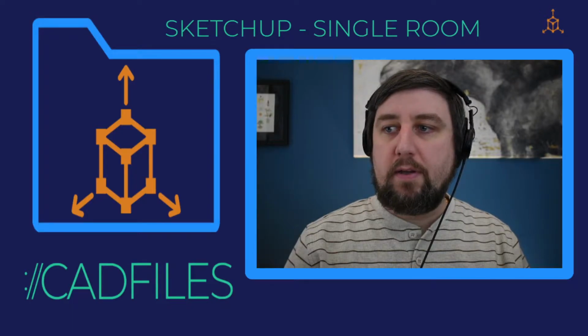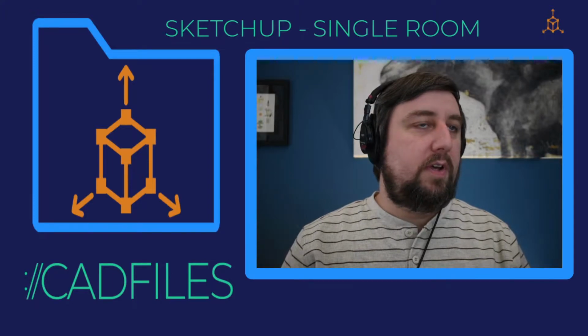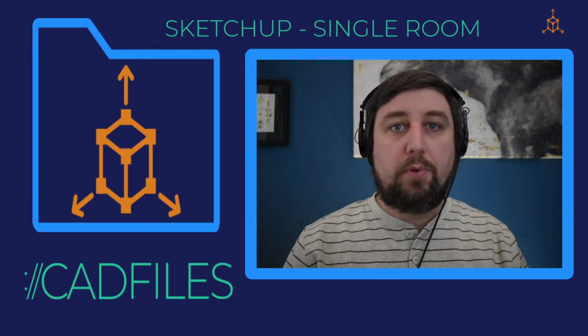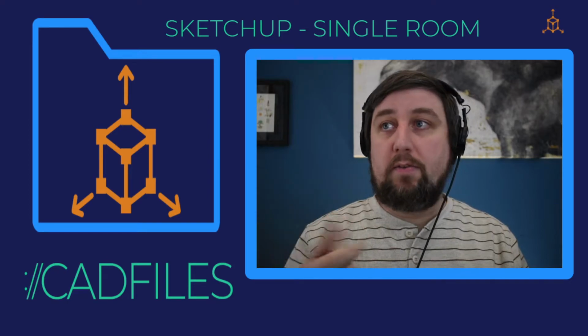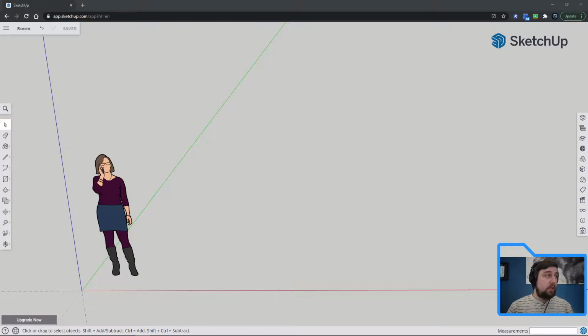Hello and welcome back. We will be drawing a room this time in SketchUp. So we're going to worry about interior, we're going to do walls, we're going to pull up the walls, and then we'll also mainly be learning new things for offset and the tags. The tags, again, remember they are like layers in AutoCAD, but we are now in SketchUp, so it's a little bit different. All right, I just did a new template, architectural, called it roomed.